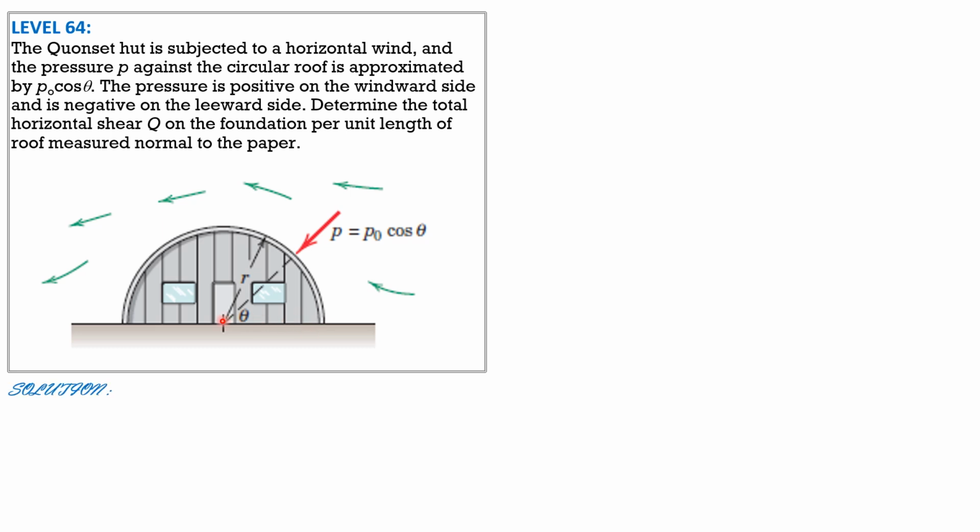So for the solution, let's have a differential element, which is a sector as shown, and the length of the arc of the sector is of course radius times this angle differential theta, and the differential force over this differential arc is the length of the arc, r d theta, then multiply it by 1 unit perpendicular to the paper or to the screen to make it differential area. So this pressure times differential area becomes differential force as shown.